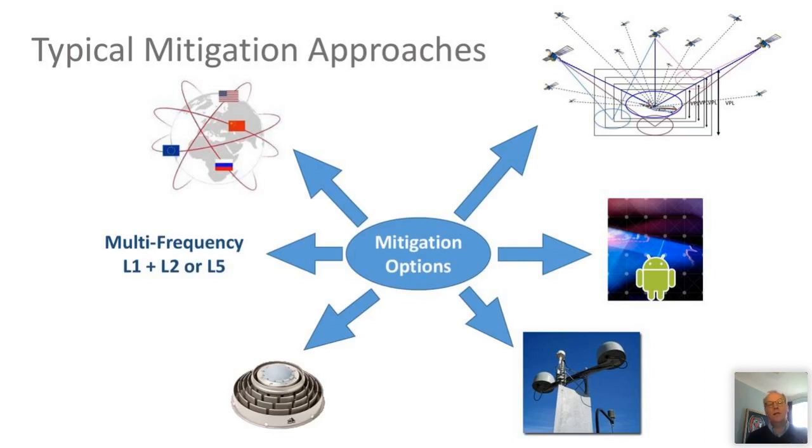And if you look at the little indicative diagram with the 4 GNSSs on the left, you can use more than one system. So you can use more than GPS. You can combine different systems together to give you more satellites. That helps to improve performance. It's not necessarily accuracy, but it does help to improve performance. And you can also use multiple frequencies. That's starting in cell phones and is quite common in other areas as well. And that helps to remove the atmospheric ambiguity and can give you accuracies of about 1 meter rather than about 5 to 10 meters.